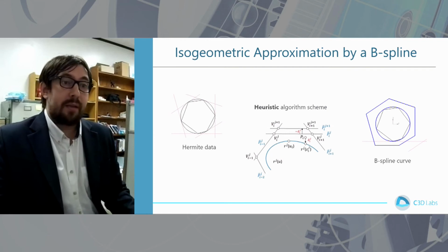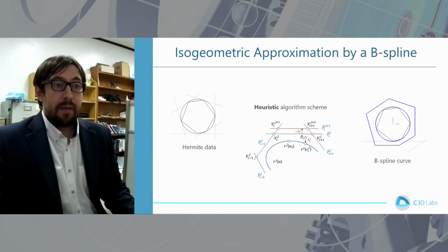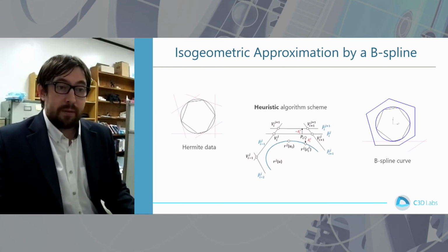The algorithm is heuristic and is similar to manual editing of S-polygons. Initial tangents at V-curve points are used, and tangent intersections are the S-polygon's vertices. In the current iteration, the point-to-spline distances are estimated on the S-polygon. To minimize errors, a tangent is shifted parallel to itself by the error value. Then the iteration is repeated, making the proposed isogeometric approximation algorithm a heuristic geometrical procedure.